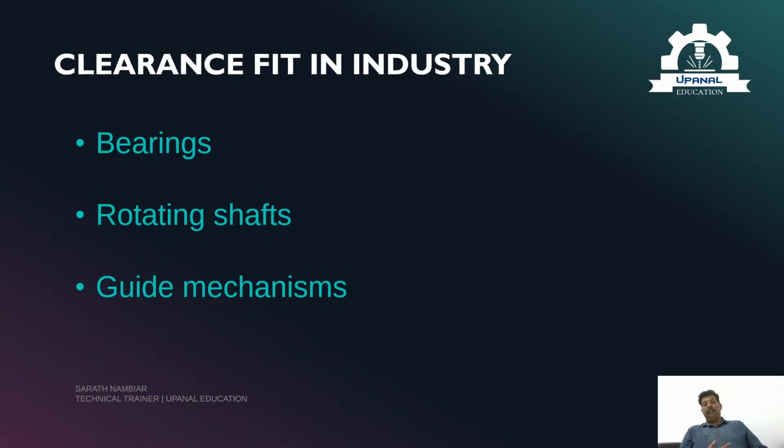What will happen without clearance? For example, I have put a bearing on my shaft. If it is very tight, will the bearing turn? The bearing should turn, right? It won't turn. It will be very tight. What will happen? The friction increases, heat builds up, and parts may seize. That's the importance of clearance fit.